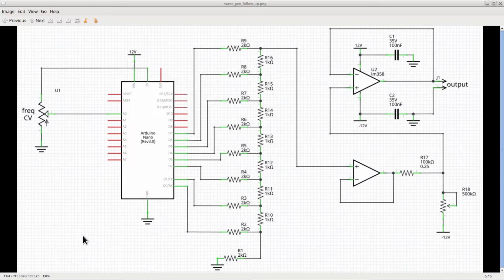Second, I used the pins from D0 to D7 for the 8-bit output that goes into the digital to analog converter. I did so because that way it is going to be easier to control the pins simultaneously, which will speed up the software execution. More on that later when we will take a look at the software.